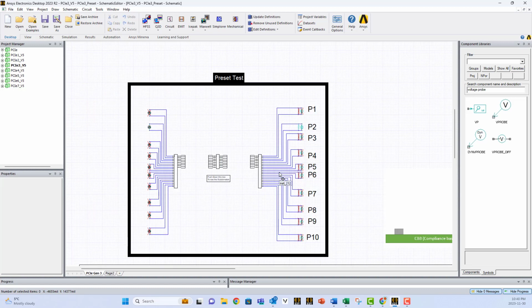The circuits that we have here are just the beginning, and users can construct an unlimited number of circuits based on them. The most important thing to remember is that all the necessary building blocks and setups exist in this template. Make a copy of them and run your circuits. Start first by obtaining the S parameters for your PCB, whether it's simulated or measured.